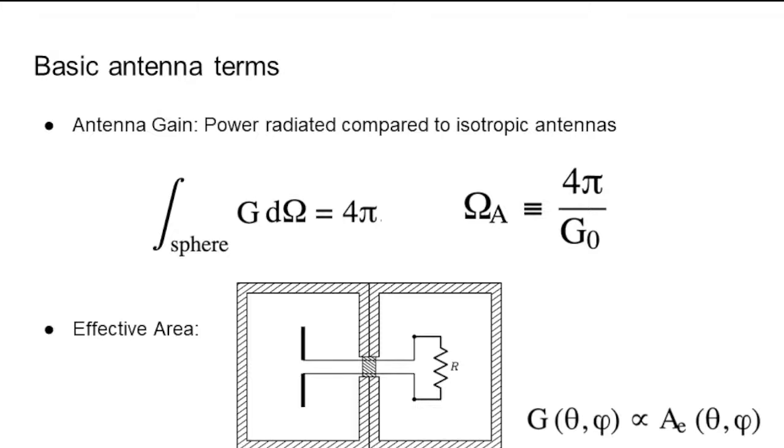It never existed. But the question is, in a given direction, how much extra you are radiating compared with that isotropic antenna. If you have a very high gain antenna, which is what people in communication systems desire, a lot of your power is transmitted in a very specific direction on the sky. The rest of the places it doesn't really go, compared to an isotropic antenna.